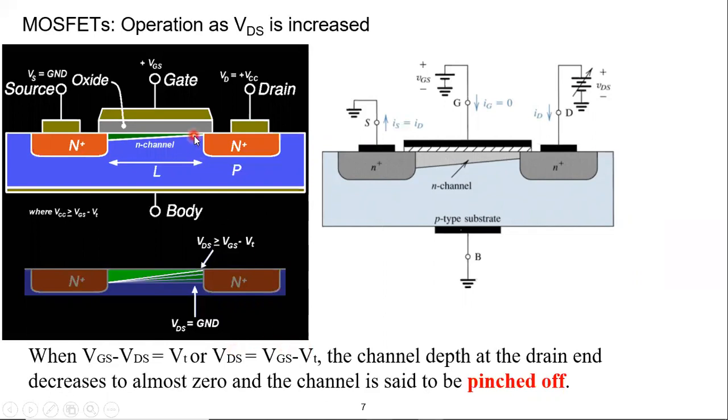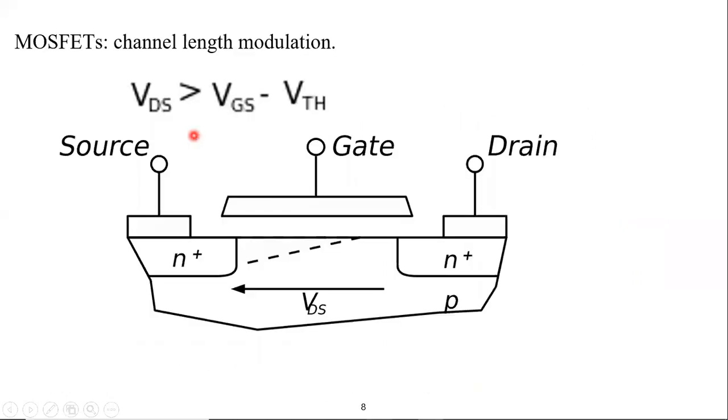What if we increase the voltage above VDS? Now the pinch-off point will start to move toward the left. As you can see, this area becomes an area with 0 electrons, with 0 holes. So this area is now a depleted area. Electrons will move from the source till this point, and due to the very high attraction force by the drain, electrons will tunnel through this depletion region.